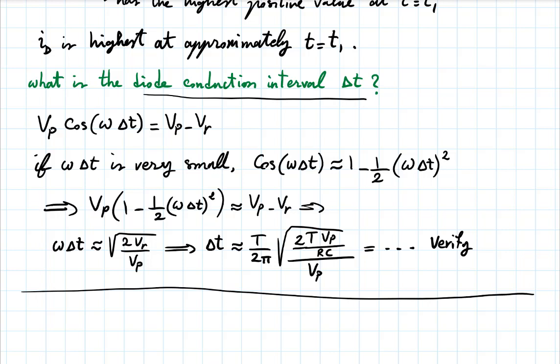It could blow up the diode, right, if it can't handle it. Or, think about it in another way, it will not allow the capacitor to charge at the rate that we want if the diode cannot handle the maximum current that it needs to. Okay? So this is something that you have to take into account. And the maximum that a diode can tolerate, you'll find from the data sheet.